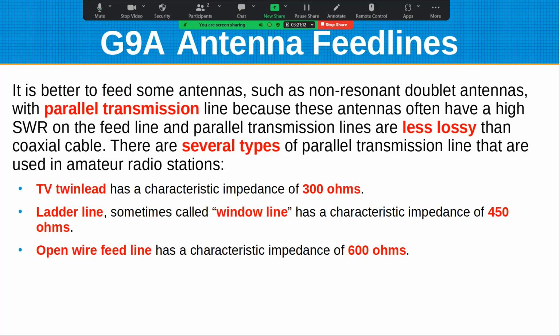One of the most popular would be the Carolina Windom. It's often an off-center-fed dipole where you're feeding about one third from one end. There are a couple of recipes on the length variance. And then at the feed point, you use a 1-to-1 transformer, and you can run coax this way. I've used those, they are very good antennas.